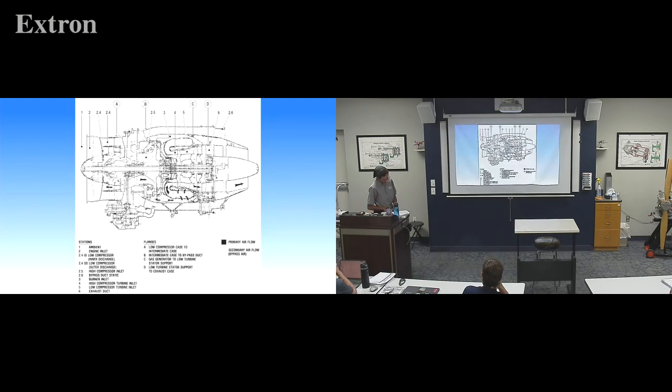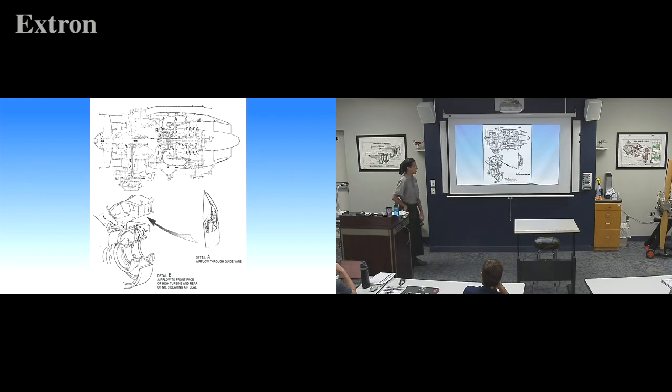Here is a diagram of our Beech jet engine, a JT-15. So our core airflow comes through here. What do you think this is? So we come through our compressor. Yes, I heard it, diffuser. And it comes into our combustion and out. And then what is this airflow here? Yep, fan bypass air there. And then here is where all our cooling air to all our accessories go.